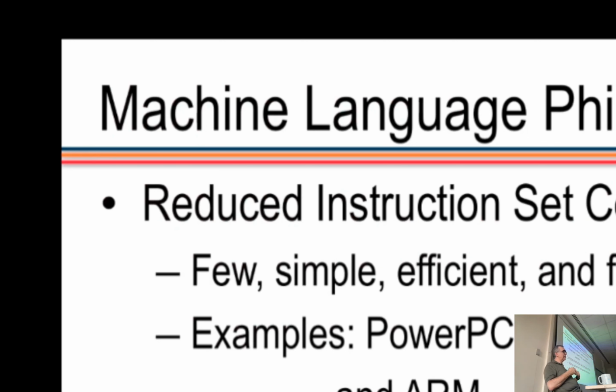But the hypothesis is many things can be implemented with a small number of steps, and with a small chip size, because when chip size becomes smaller, heat dissipation reduces, power dissipation reduces, you can go higher in the clock cycle, and also you can be more efficient. That means if you make the chip bigger, it will be less efficient. So reduced instruction set computing is relatively powerful, I think, to me.